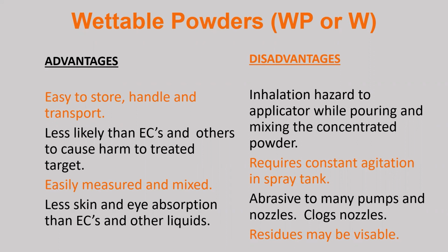The one thing with the wettable powder, it does require constant agitation, whether it be jet or paddle agitation, mechanical agitation of some kind. And it can be abrasive to the pumps and nozzles, and can clog nozzles, screens, and tips if it's not completely dissolved. And you may actually have visible residues.